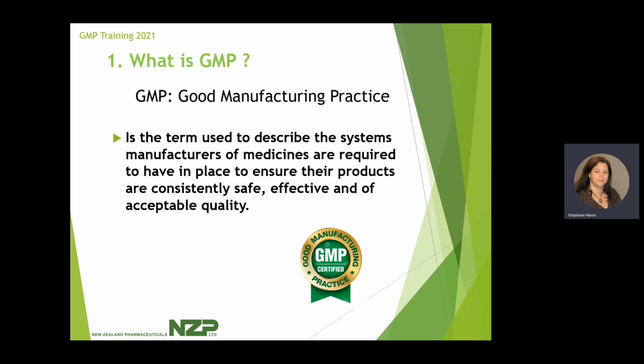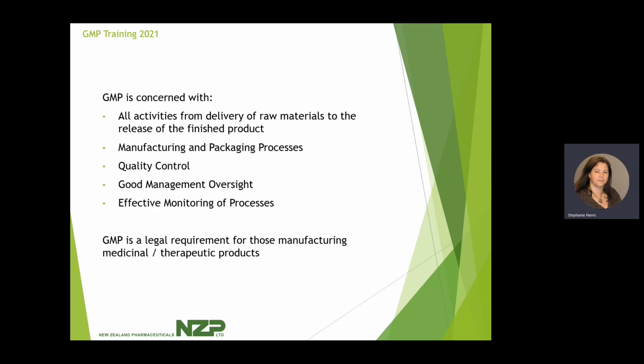What is GMP? GMP stands for Good Manufacturing Practice. It is a term used to describe the systems manufacturers of medicines are required to have in place to ensure their products are consistently safe, effective, and of acceptable quality. GMP is concerned with all activities from delivery of raw materials to the release of the finished product, manufacturing and packaging processes, quality control, good management oversight, effective monitoring of processes. GMP is a legal requirement for those manufacturing medicinal and therapeutical products, as we do at NZP.